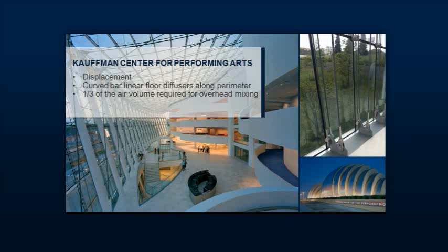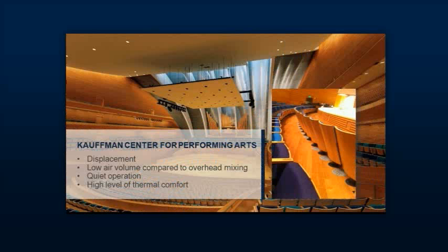Now, one way that I often can help you settle on a design, and also your end user a lot, is a mock-up. This image shows a mock-up that we have currently installed in our lab in Atlanta for a hospital room that's using chilled beams. Now, this is the four-way discharge beam, and you can see a little bit of the theatrical smoke and supply air in this image. This wall is hot or cold based on the wall requirements of the building structure.